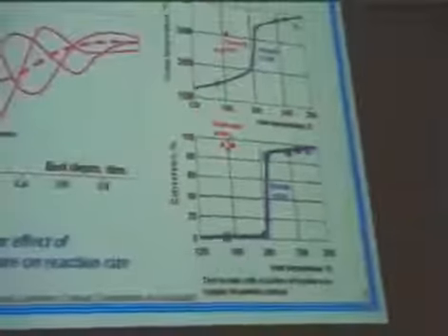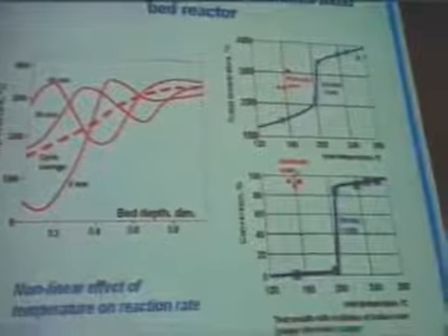For a reversible process, I can increase the degree of conversion because I will work at lower temperature at the outlet of the packed bed of the catalyst. And second, I can decrease the amount of energy that I spend to reheat the gases before the packed bed of the catalyst.